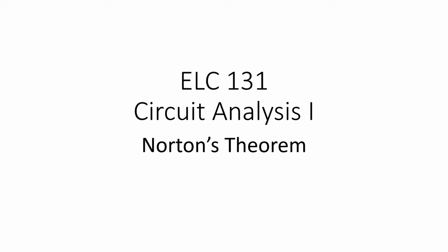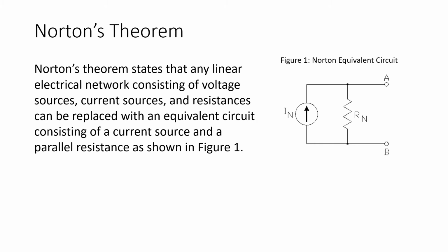This is ELC131, Circuit Analysis 1, and this video is on Norton's theorem. Norton's theorem states that any linear electrical network consisting of voltage sources, current sources, and resistances can be replaced with an equivalent circuit consisting of a current source and a parallel resistance, as shown in Figure 1.